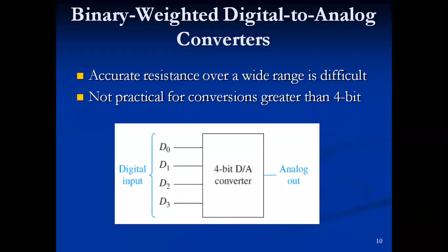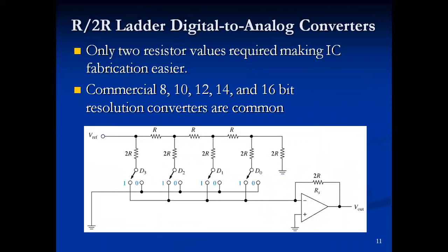But even those have a tolerance level. You realize that? So you can get something that's labeled 25 ohms, but it's really more like 26.1 or 25.8. There's a tolerance, a margin of error. So that is not the best design, believe it or not, because of the errors that we have in our manufacturing.